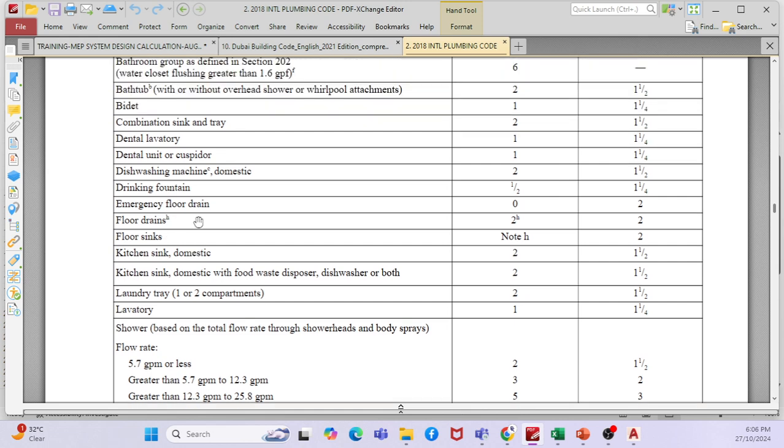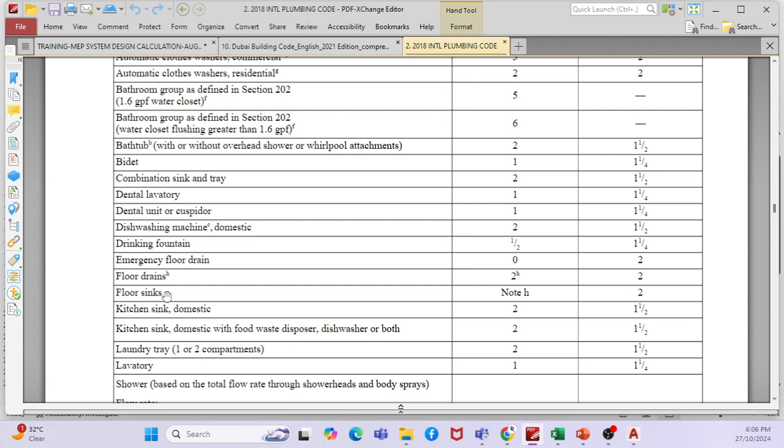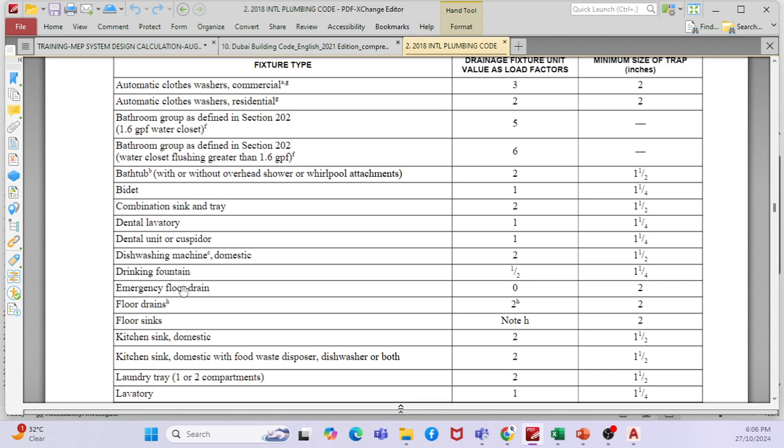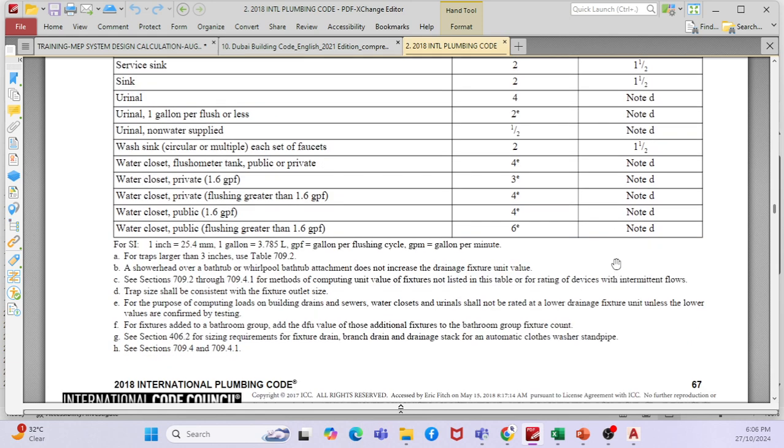Yes, but the sizes of catch basin start from 110. Floor drain usually from 75 mm. Yeah, floor drain is 75 mm. Basically speaking, there is no standard given for the catch basin, but we can refer to the manufacturer. If the manufacturer designed for 110 mm, that means you directly take that as the pipe size, right? The minimum pipe size from the trap. See, if you go further down, the standard has clearly mentioned here.